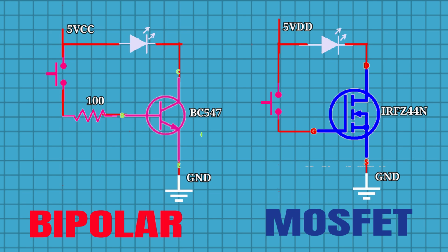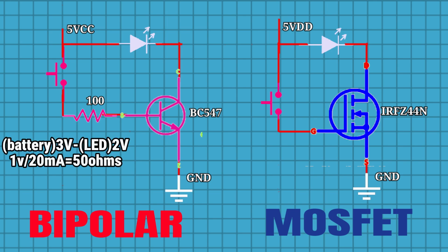This is because I am using a 3 volt supply and my LED is a white color, and the voltage drop for a white LED is around 3 volt. Maybe if you're using a red LED, yellow LED, or any color, make sure to check for their voltage drop to know which resistor to use. Like for a red and yellow LED, the voltage drop is around 1.8 to 2 volt, which requires, if you're using a 3 volt supply as I am, a 50 ohms resistor. This will help prevent your LED from getting burnt.